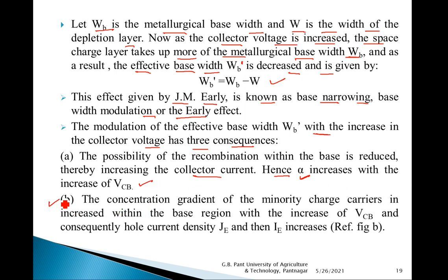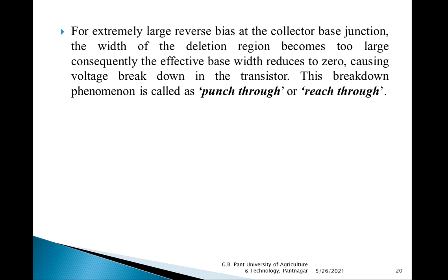Now the second consequence is that the concentration gradient of the minority charge carriers increases within the base region with the increase of VCB, and consequently this hole current density JE, and then IE, increases.